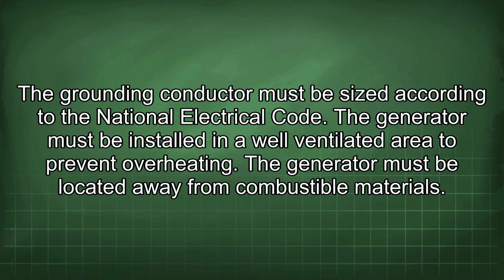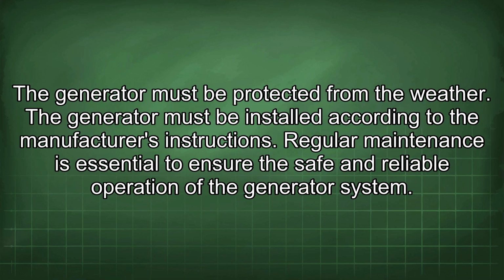The generator must be installed in a well-ventilated area to prevent overheating. The generator must be located away from combustible materials. The generator must be protected from the weather. The generator must be installed according to the manufacturer's instructions.